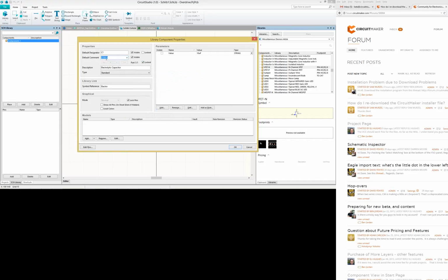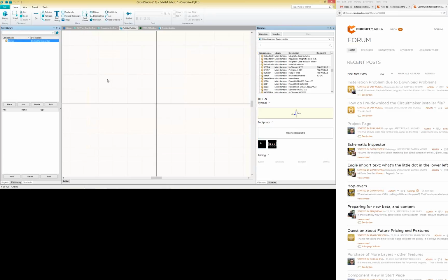You guys are quite familiar with Eagle, of course, so one equivalent function is like the greater than name, greater than value strings in Eagle. It's kind of the same thing. Anywhere where you see parameters in Altium products, you can reference them using this equals for schematic, or the decimal point if it's in a PCB. So this means that the comment will always come from the parameters inside the component. So I've got this part.